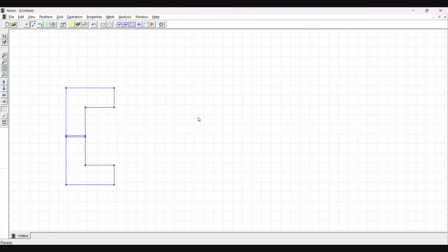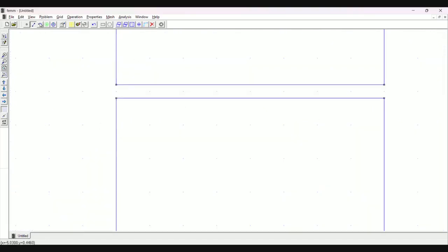I'm just applying the same. Yeah, see. Let's zoom in over here. We can see the air gap. We can also measure. I'll show you how to measure. So draw line and right click it, it's getting selected. If you are doing double tap, you can see the dimensions. So here if you see, it's 0.1 mm. That's what we wanted. So I'm just deleting that line.